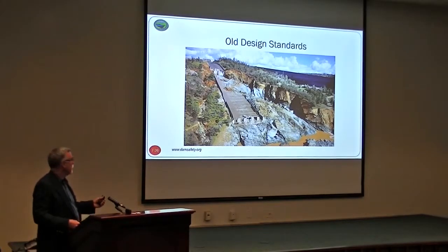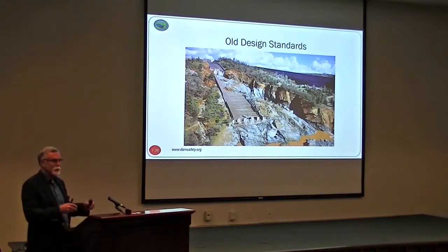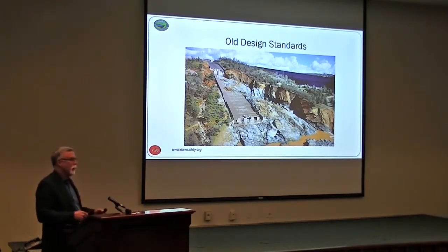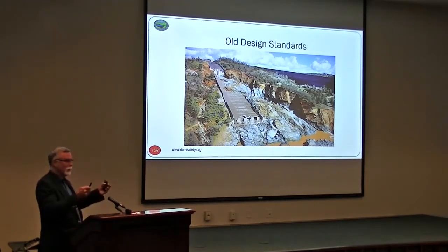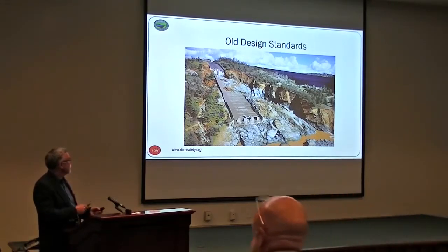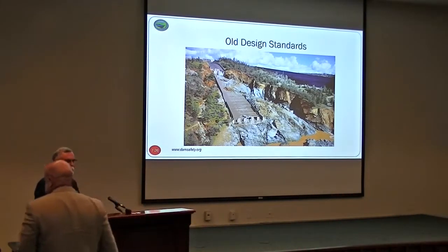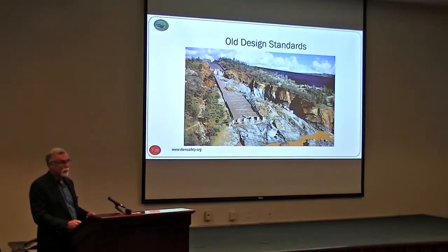This spillway was designed by well-qualified engineers at the time, but the design standards today are a lot different. As I mentioned before, this spillway has been inspected by numerous high-quality engineers. If they would have looked at the original design drawing, they would have noticed the weaknesses of this spillway. It had cracks. There was a history of repairing cracks. The drains under the spillway, there was a history of those flowing excessively. There were some warning signs, but nobody really paid enough attention to it. It cost the owner $1 billion plus.